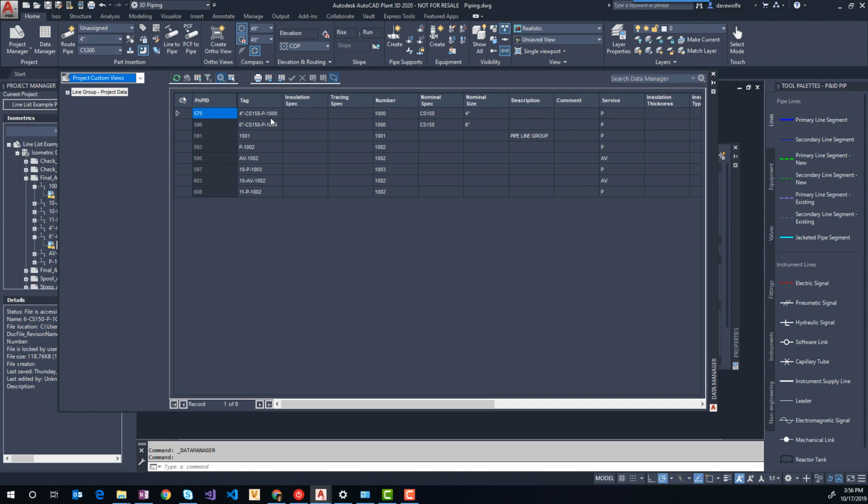Different components could be in different spots. Maybe someone started this at a control station. They might have accidentally created the tag under the control station size. When we route up a pump, usually we're going to increase right off the pump, but when we start the line, we're going to route a smaller size. So we might have started at the pump at 2 inches and gone to 3 inches right away, but then the rest of the line is called 2 inches.